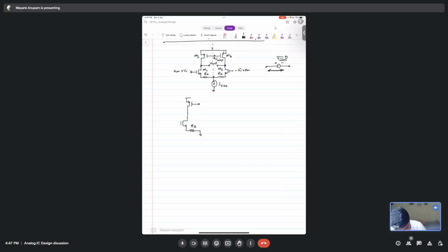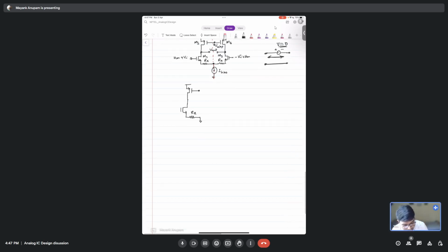If you make V equal to zero between these two terminals, what is happening effectively here? A short circuit, isn't it? Yes, sir. Similarly, if you have a current source between two terminals, what is the purpose of a current source? Its purpose is to make sure that a current I naught flows here, in one direction, right? Now, if you have to desensitize it, what will you do? Open circuit, sir.